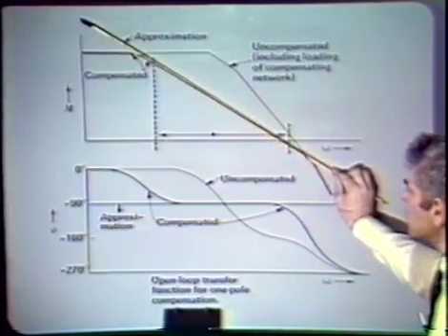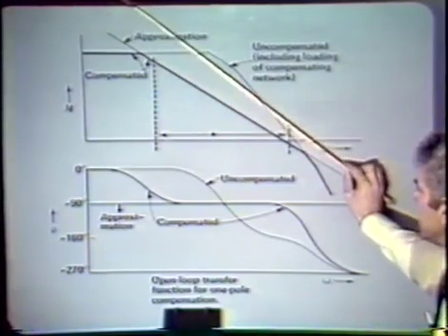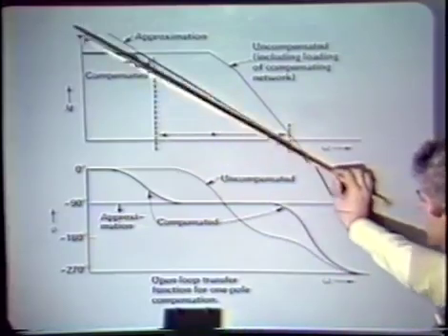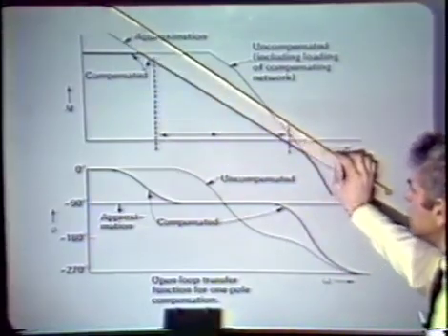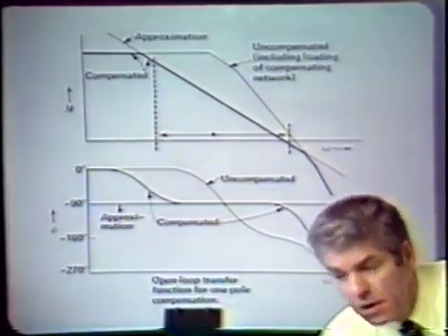As we decrease the value of C sub C, the curve moves up, implying wider bandwidth out of the amplifier itself. Now, as we decrease C sub C, the unity gain frequency of the amplifier itself will increase, and in fact may very easily go above a megahertz for certain values of C sub C.